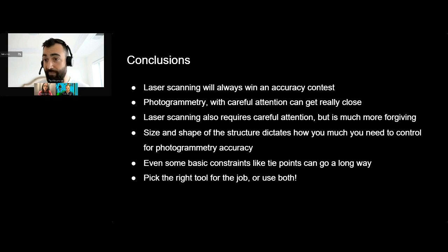Well, I think there's two options you could take. I don't think terrestrial laser scanning is well suited for that, just because coastlines, to me, that sounds like a long area, just a lot of distance to cover, and setting up these stations would take some time. Aerial laser scanning, a lot of LiDAR payloads out there, a lot of LiDAR drones that are perfectly suited for that, is the way to go there. And maybe even handheld if you want to walk that coastline, depending on what the access is like.